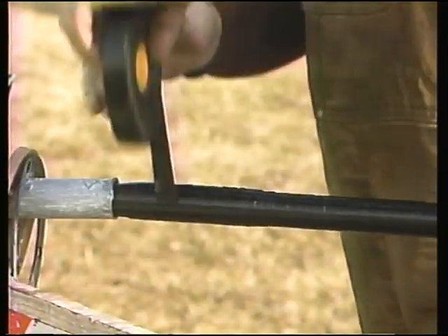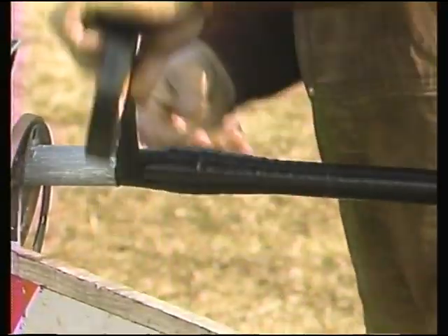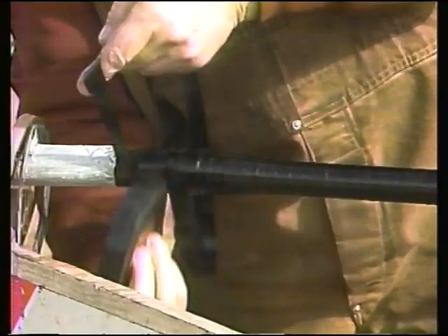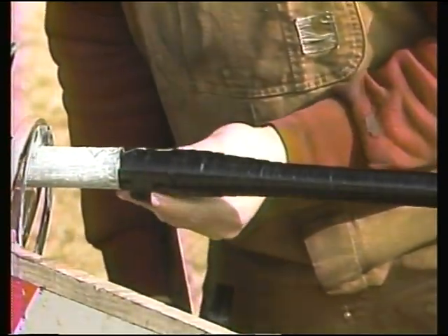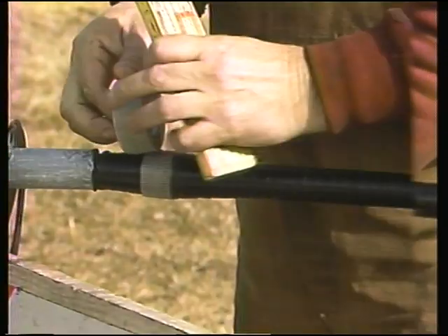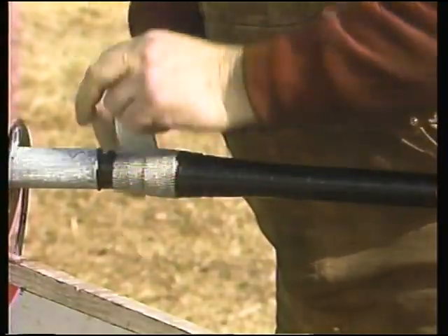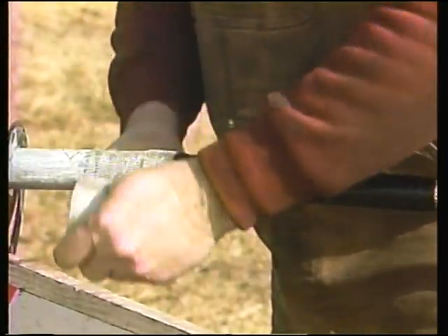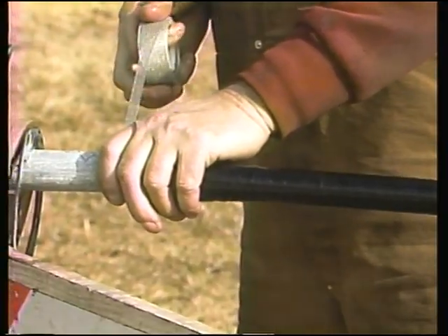The workman uses the same insulating tape to build a stress cone. He begins the cone at the edge of the lead layer and builds it up until it conforms to the size and shape specified in the instructions. He then extends the cable insulation shield to the top of the cone by applying a braided metallic shielding tape. Beginning at the middle of the stress cone, he half-laps the tape back to the lead cover.